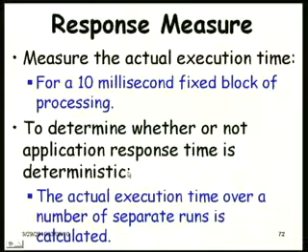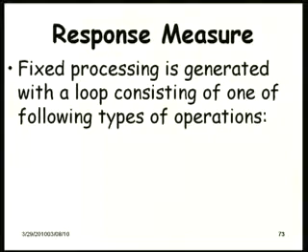Otherwise, in your scheduling routine, you can't really assume that it takes that much time. You have to take the maximum in that case. Sometimes it takes less time, sometimes it takes more time. Then in scheduling analysis, you will have to take the maximum time. So, here you will run it several times, and each time use the time of the day clock_gettime, and measure how much time it takes.